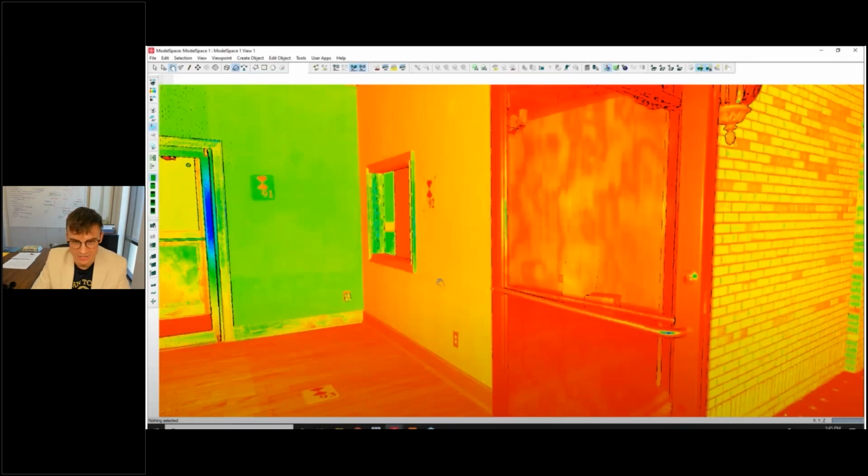So where to place targets? Targets are especially important in critical tie-in areas like doorways, if you remember from scan planning. If a rotational error is introduced at a critical tie-in area, an entire wing of a facility can become misaligned. Think like a lever arm.